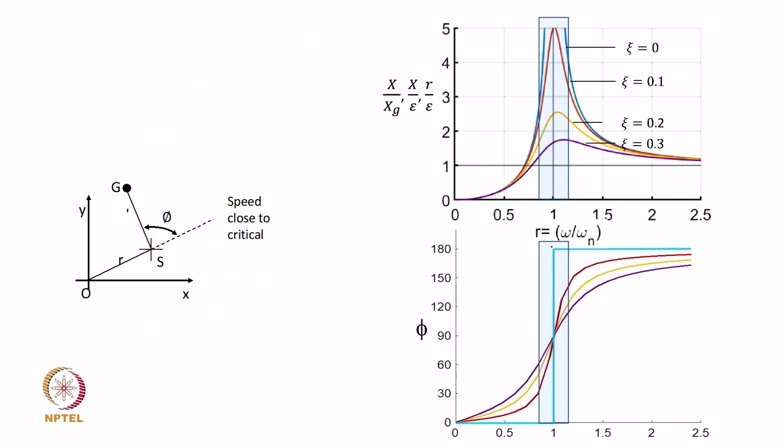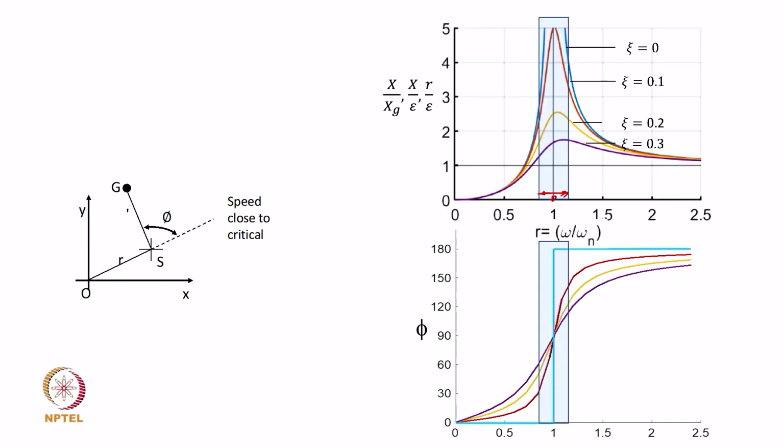Now, this is very similar. In the past we have discussed how the forces are acting at different speeds of rotation. So, supposing we look at the range of speeds close to the resonance or critical speed. By the way, this resonance in a rotor bearing system is usually referred to as a critical speed. That is the speed of rotation, which is the excitation frequency. When it is close to the natural frequency, then you have resonant vibration amplitudes.